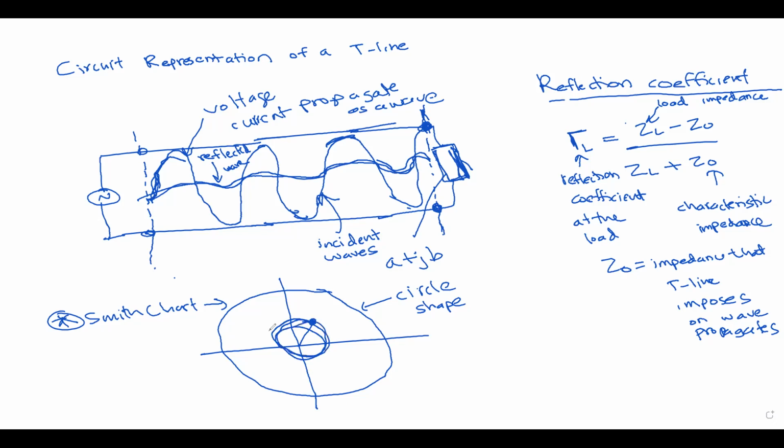I will show you a Smith chart later. So the Smith chart is used to match the output impedance, the load impedance, to the transmission line by following some pre-known steps. So we can move the reflection coefficient to another location using this design, or Smith chart based design that we do. So we can use the Smith chart to do the matching.